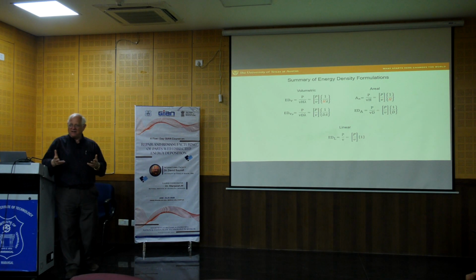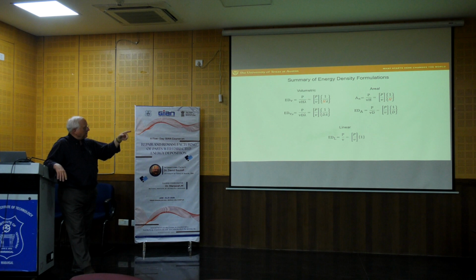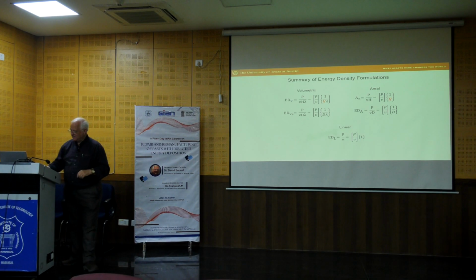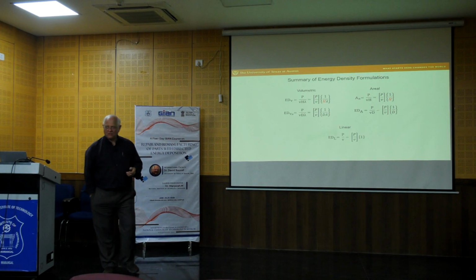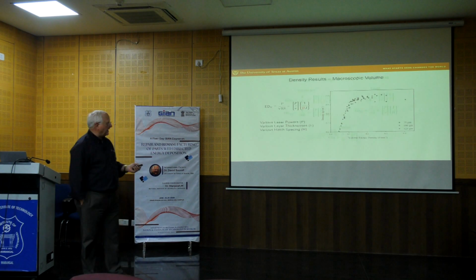It was done with nylon, not with a metal. But to ascertain which of these is really the best, in this case I varied the beam size and diameter and the layer thickness so that we could see and probe more completely which of these was doing the best job of predicting good density and good mechanicals.